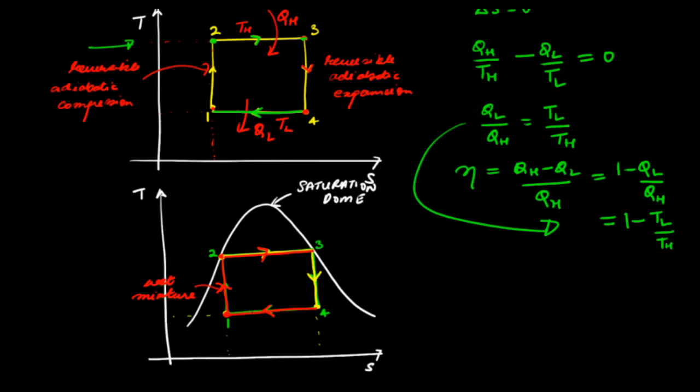There are other choices that one can have for operating a Carnot cycle on this TS diagram. So another way to do it is, let's say, this cycle. So this cycle shown in blue color is another way we can implement the Carnot cycle, but it's even more complex than the previous cycle, and that's because here the heat addition partly takes place from this state to this state at constant temperature and constant pressure.